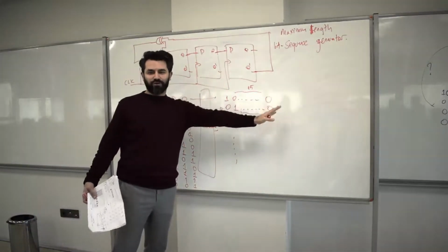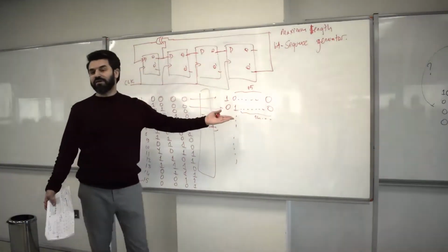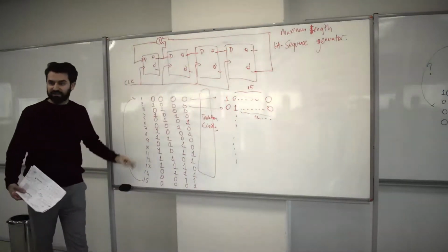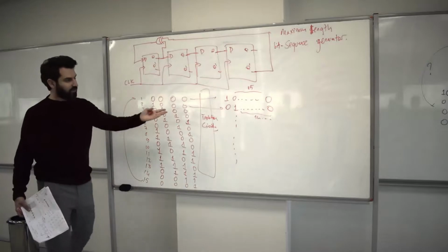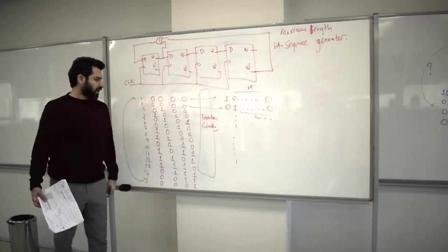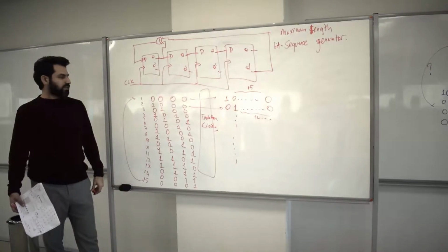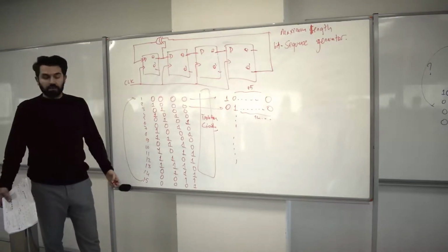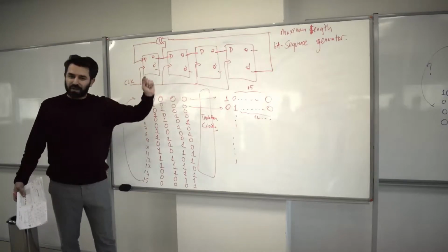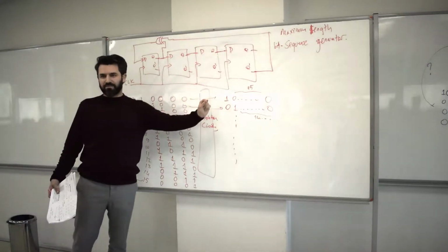That would generate the same format you have with the ring counter. But that's not in order. You can see that it's not in order, so it's not going to generate the way you like it. However, of course, you can still use a decoder, but now you have to map the outputs of the decoder to the appropriate locations. You know what I mean?